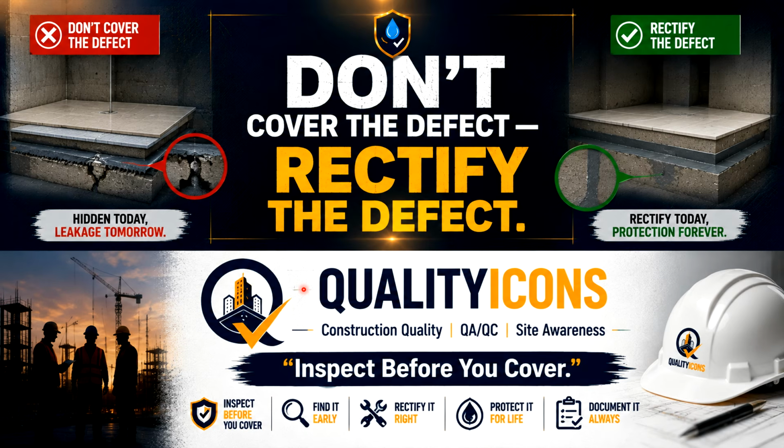In toilet B, the team follows the sequence. Initial ponding detects a defect, the defect is rectified, ponding is repeated, waterproofing is applied, protection is provided, and the final 72 hours ponding is completed. Then the toilet is released for tiling. This is the difference between finishing the activity and controlling the quality of the activity. Don't cover the defect, rectify the defect.